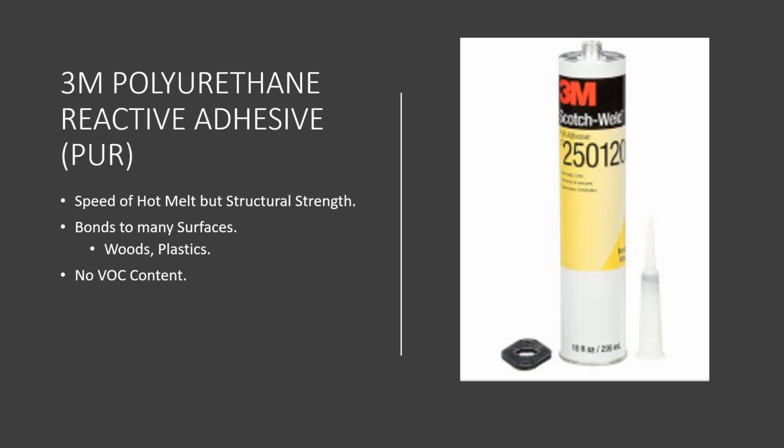It bonds to a lot of different surfaces, including woods and plastics, and it's 100% solids, so no VOC content, so very environmentally friendly. It is dispensed at a hot temperature and then cures very quickly. It is a really good solution for bonding wood structurally. So instead of using wood glue that sets up really slow, or wood glue with fasteners, it will eliminate the fastener step. It will bond to wood very, very quickly.